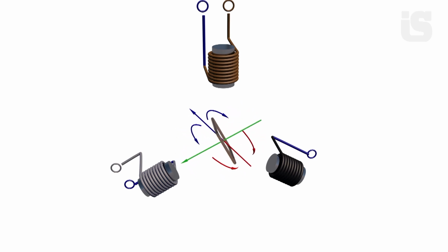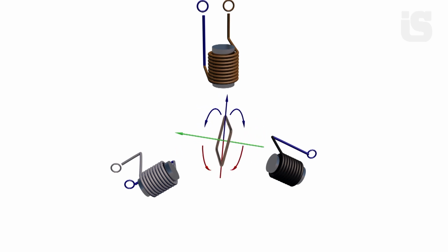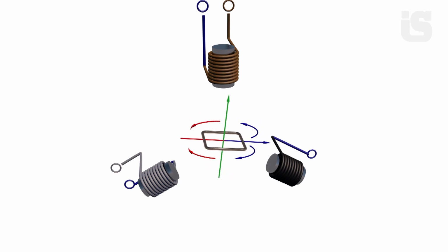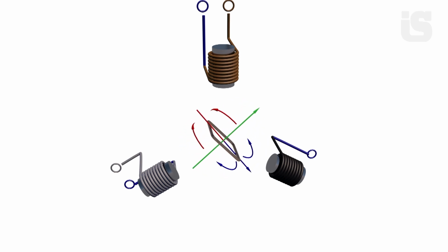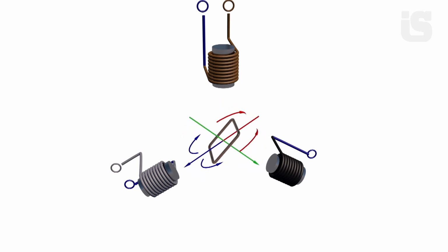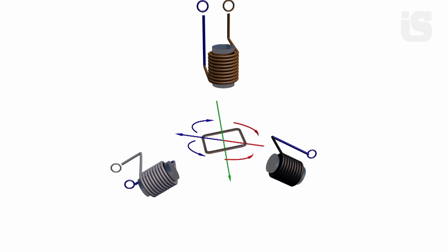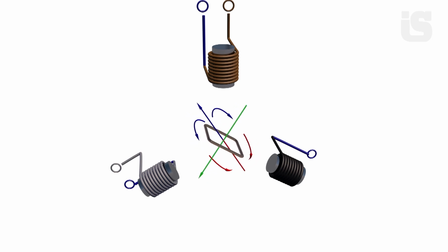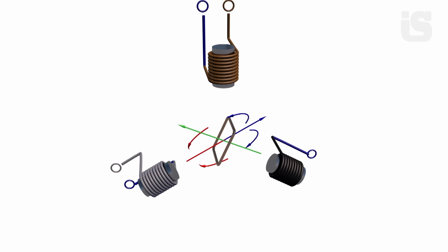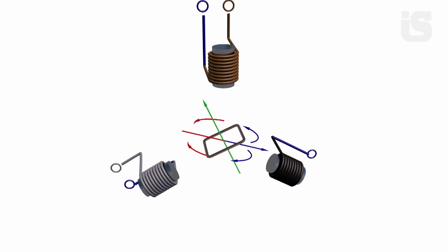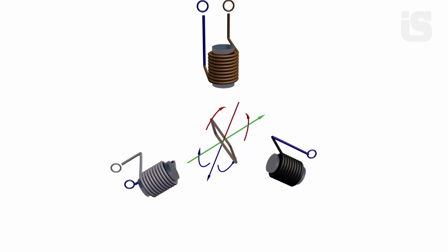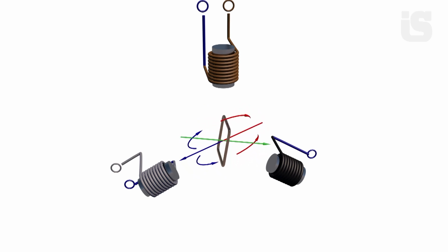A brilliant solution. The field created another field, which in turn converts the force of the electromagnetic field into mechanical energy and performs a rotational motion. In this case, the rotating magnetic field of the stator will always rotate faster than the frame. This is because if the field does not outpace the frame, the magnetic field lines will not intersect, and the frame will cease to generate current in a magnetic field.